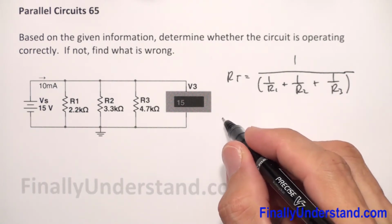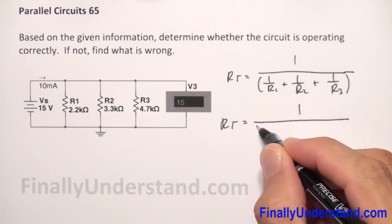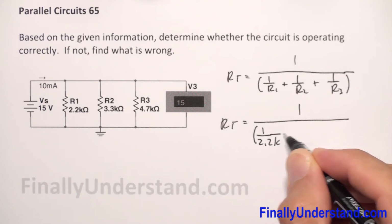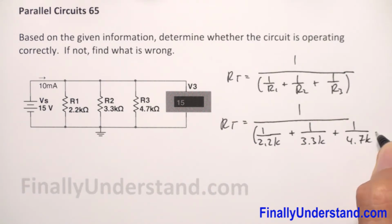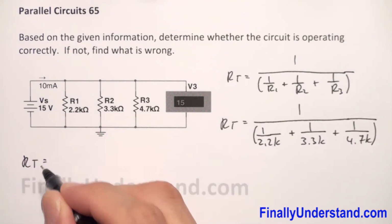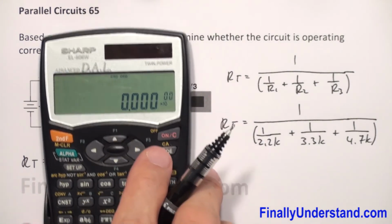So we have R total is equal 1 divided by, open parenthesis, 1 over 2.2k plus 1 divided by 3.3k plus 1 divided by 4.7k. Now we're supposed to use the calculator.